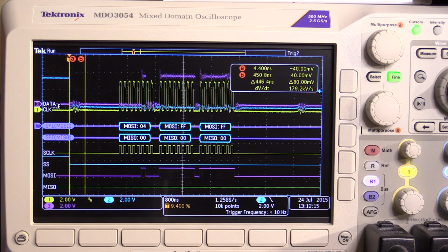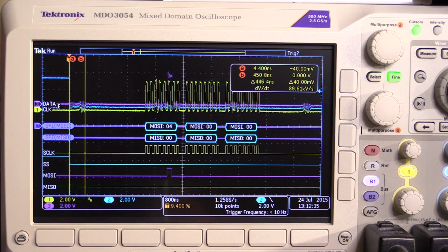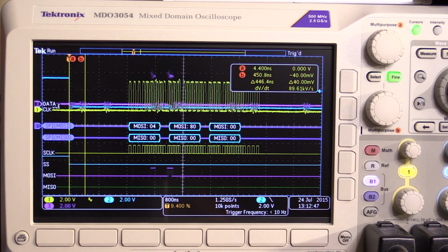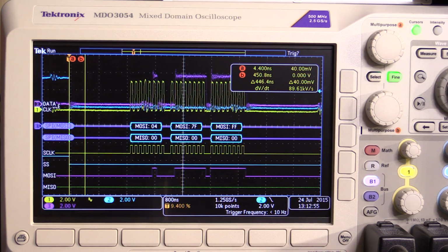So if I output 65535 on channel 1, I get 0 because I'm sitting in bipolar mode, sorry, as I said. If I output 0, it should basically stay the same because 0 and 65535 are both the minimal values based on 2's complement. But if I go 32768, I should get -5, which I do. And you can see that going out on the register there. And if I output 32767, I'll get +5 on the DVM, which I am.